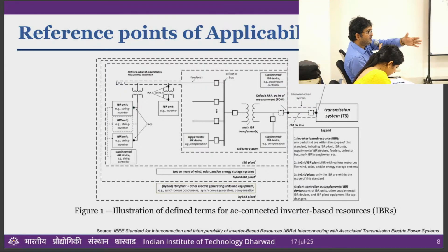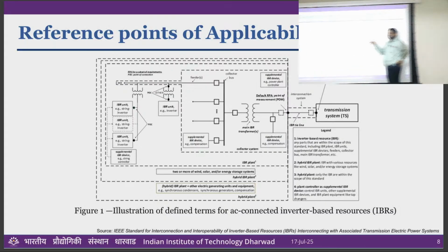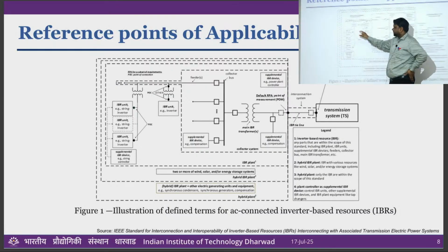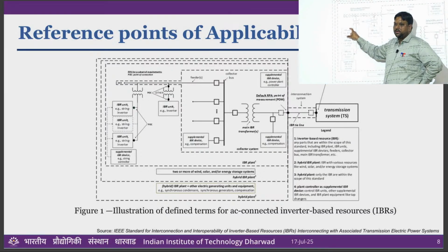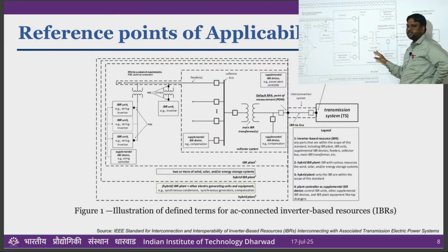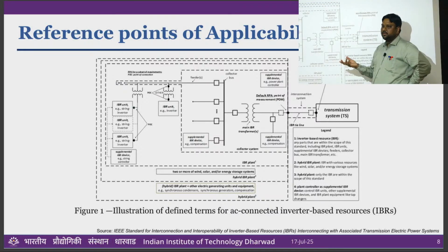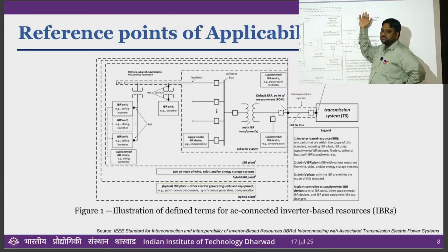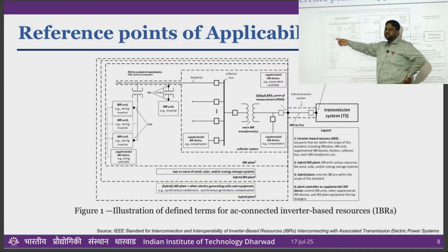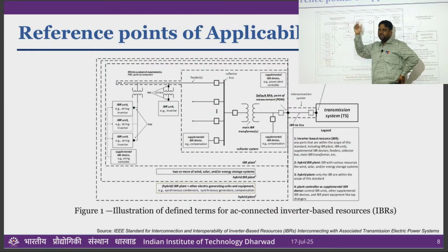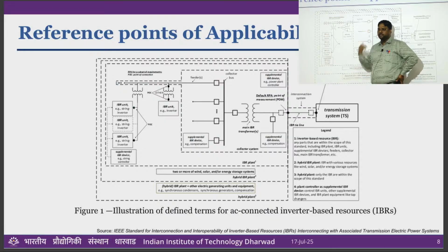The graph is basically, yes, I am saying that. Let's say your initial active power reference for this IBR unit is P1. But suddenly some change happens in the system, maybe in steady state. The PPC decides that for this IBR unit you have to change from P1 to P2. It might be P1 plus P2 or P1 minus P2.